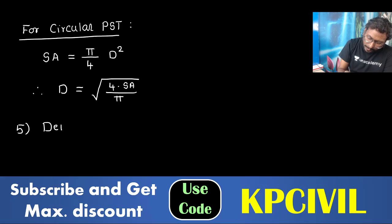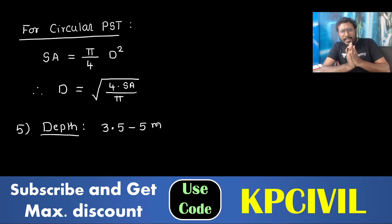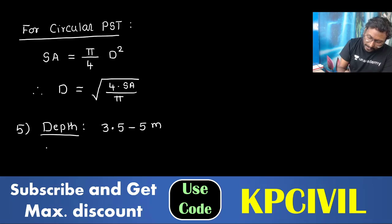For any chamber, it may be circular, it may be rectangular, depth is considered between an assumed depth of 3.5 to 5 meter. Depth of the sedimentation chamber does not influence its efficiency. So you can assume any value, but that depth you consider here. First, freeboard, whose value must be taken as around 0.5 meter.